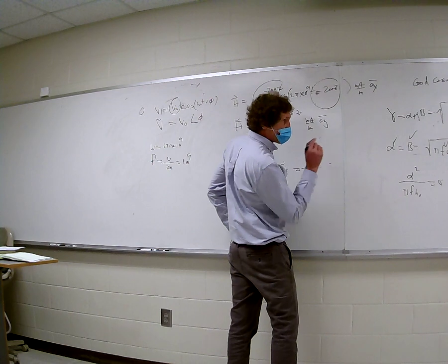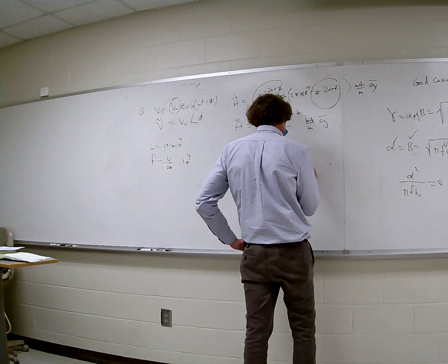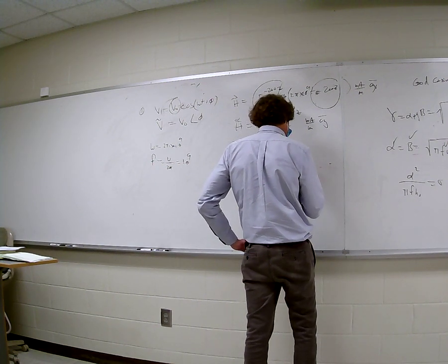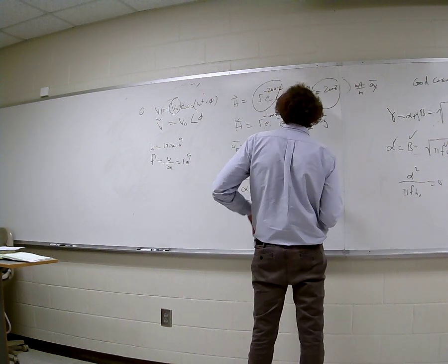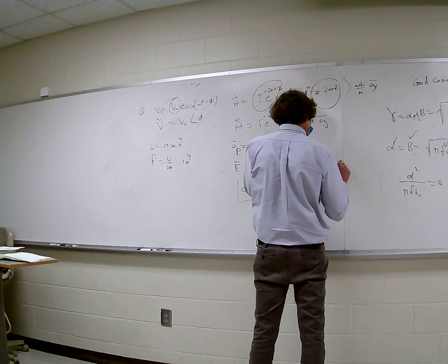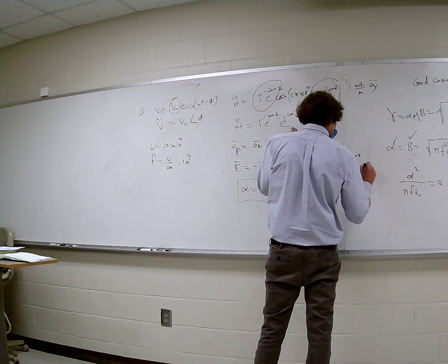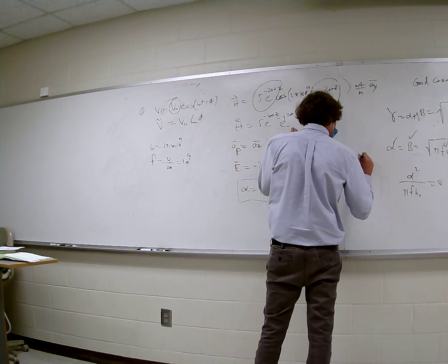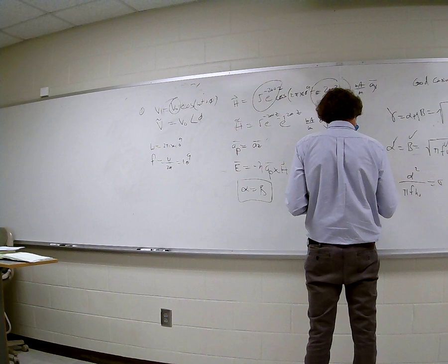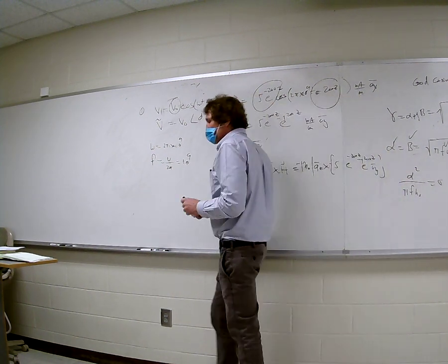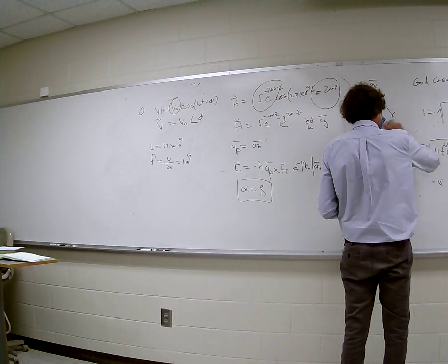It's equal to minus magnitude of eta naught times a_z crossed into H, and that's crossed into the 5 e to the minus 200z e to the minus j 200z, a_y milliamps per meter, and that goes away, it becomes volts per meter.